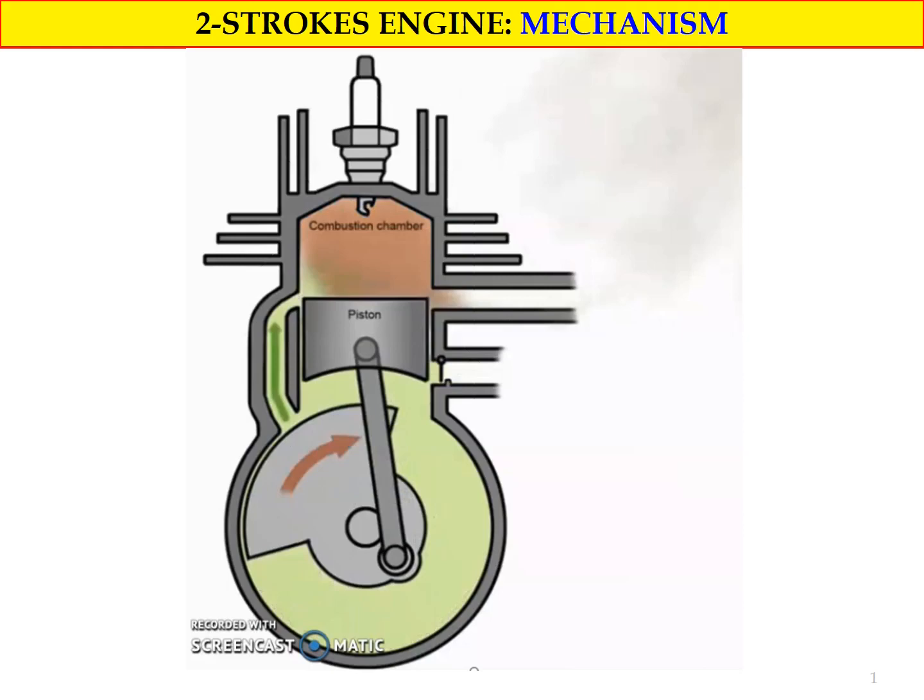The figure shows the schematic diagram of a two-stroke engine for a spark ignition engine. In the diagram we have three main ports. We have the exhaust port, where we release exhaust gas to the surroundings. We have the intake port, where we allow the fuel plus air mixture to enter the engine, and we have the transfer port, or for this chapter the inlet port, where we allow the fuel plus air mixture to enter the combustion chamber.